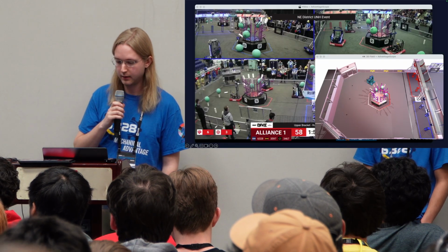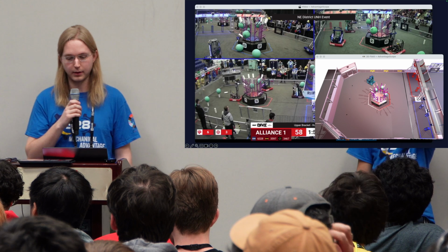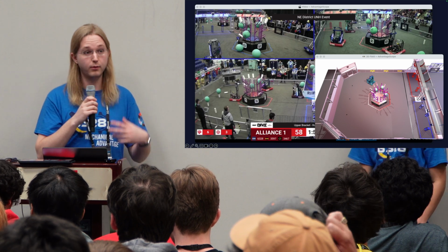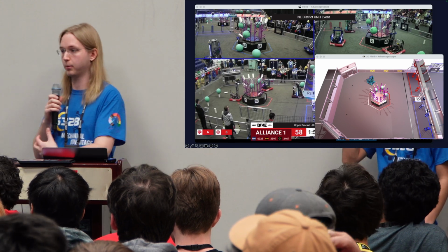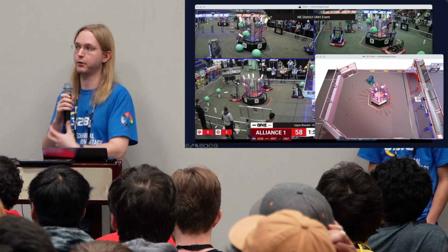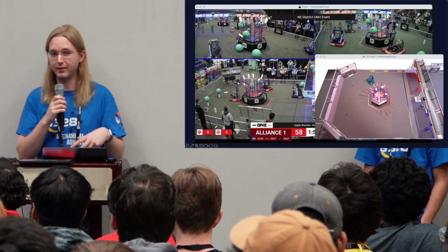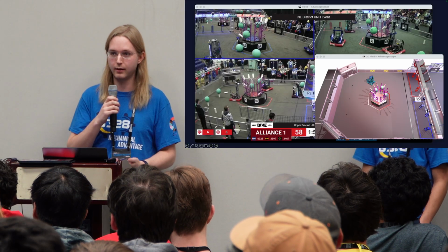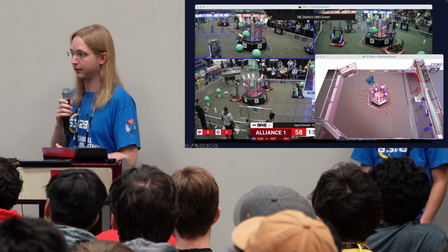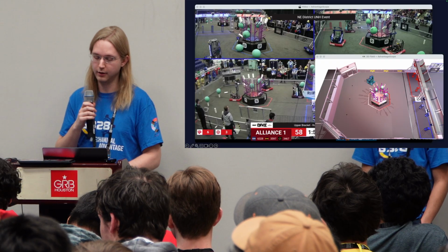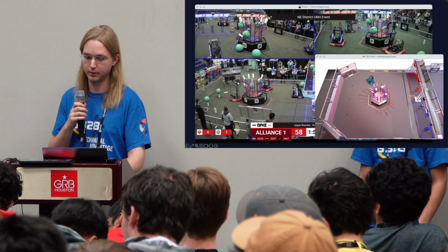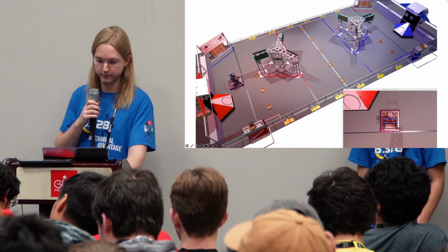And this example actually is a good example of the nuance that can come with modifying code in replay. Because in reality, if the robot received the improved pose estimates, it would have driven more forward to correct, which would give it even better visibility of the tags. That's something that can't be modeled directly in log replay, but we can confirm that the basic functionality is correct and know what we need to test on the real field while having more confidence in it.